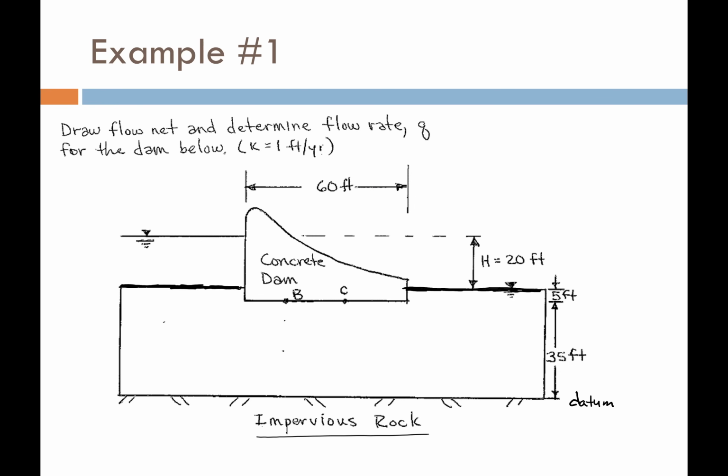Other things that I might want to point out: this dam is a reinforced concrete dam, so the base of it, where I'm trying to highlight here, is impervious. Okay, so water can't flow through the dam, it has to flow around it. And notice that the dam is keyed into the ground about 5 feet, and that between the bottom of the dam and the impervious rock we have 35 feet of this soil.